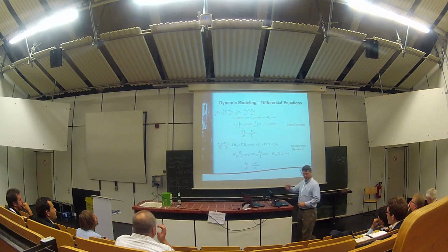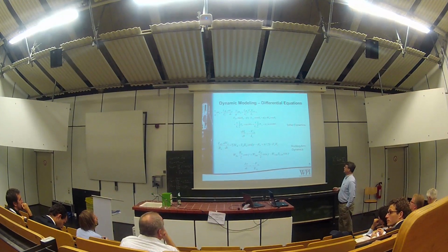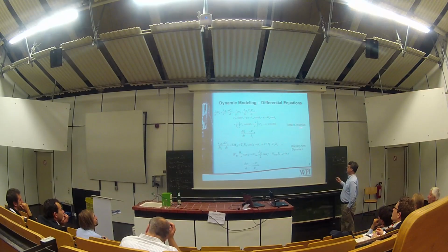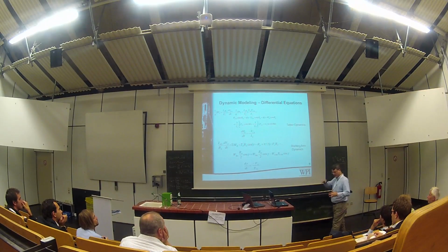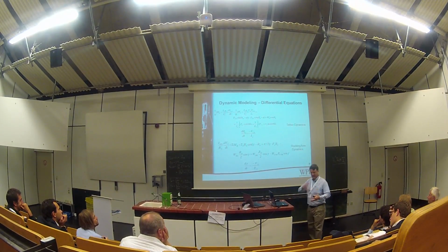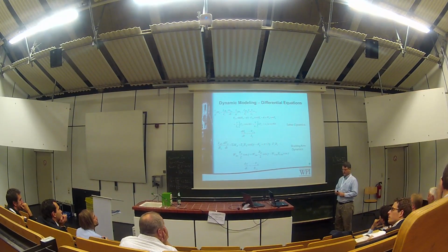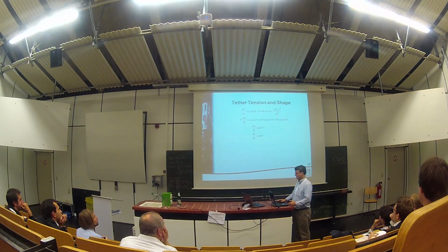I will show videos of this operating, but I wanted to show some modeling first, modeling we did to see if this could work and what it might predict. So a lot of details here, I'm just going to hit the highlights. We do have a MATLAB-based model. It's ODEs. Here are tether dynamics, all the details, but we do account for tether lift, drag, and weight forces. Here are rocking arm dynamics through that linkage. We have kinematic and kinetic linkage models. We have a simple pump model. We're not getting those details today. And we have linear, quasi-static aerodynamic models for the kite.